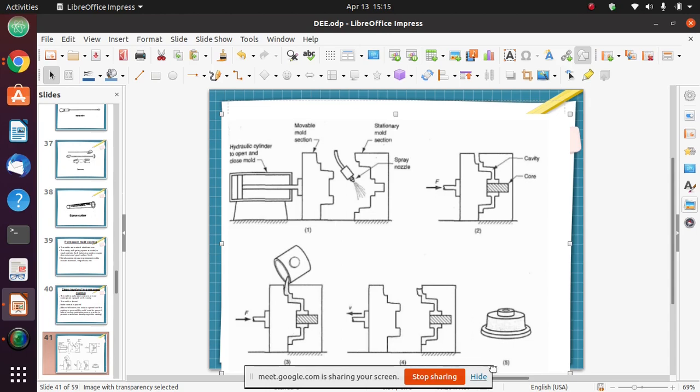When you finish the casting, the final product, utapata kuna cracks. Why? Because the mold is solid. It is permanent. It cannot change the shape to accommodate the solidification process of the casting. So you'll find that there are defects like cracking in the casting.